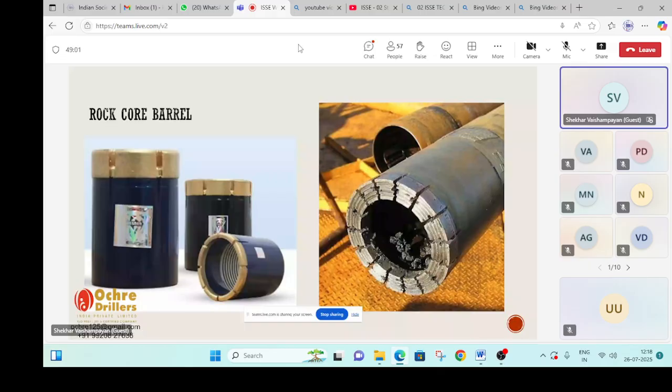Now you will ask me the question, why is this provided in a very hard rock like quartzite or very hard granite? More water channels are required, and V grooves are made in this. The V grooves on the channels provide faster drilling speed. So these are typical introductions of the drill bits. You'll be seeing this physically at site also if you happen to attend and see what is used at your site. So field permeability tests are done.